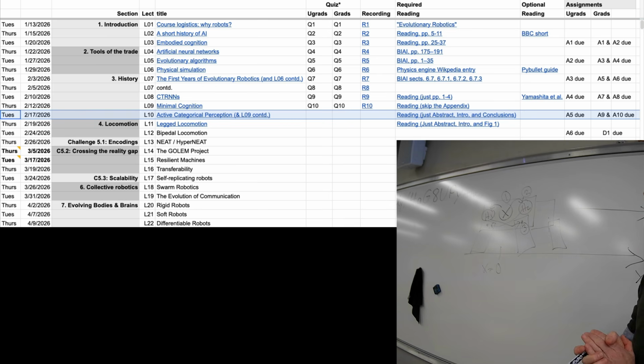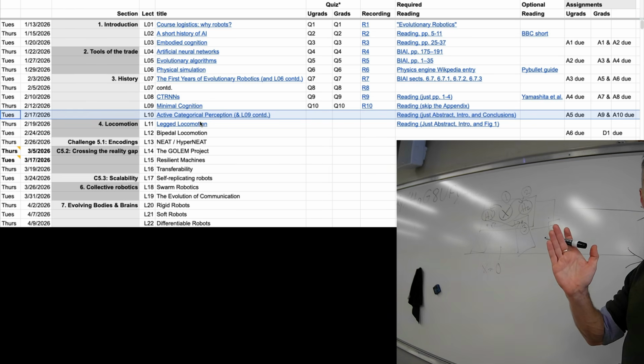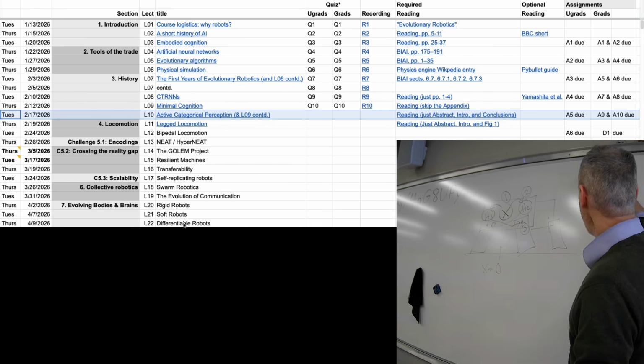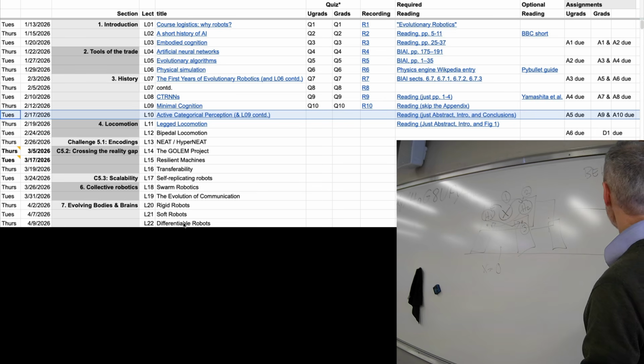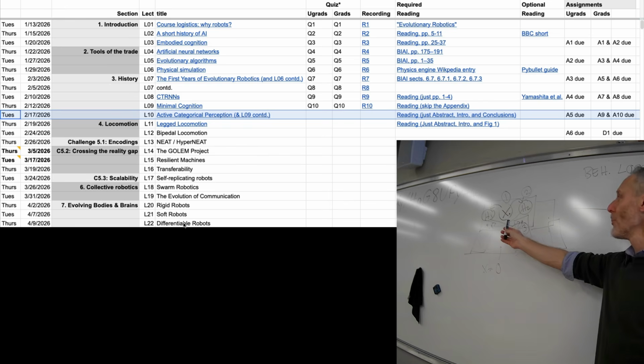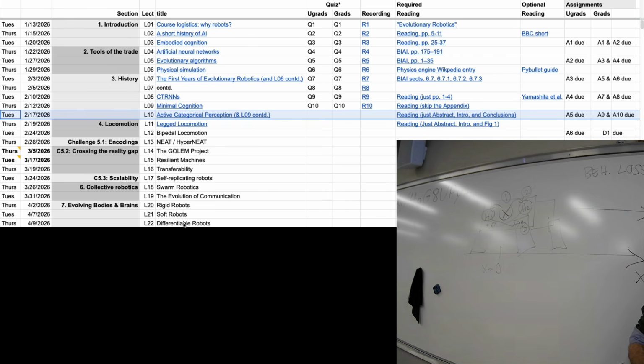At the end of the simulation, we can compute the fitness of the robot, how far it travels to the right. Now the first difference is going to come in from everything you've heard so far to differentiable robots. Instead of computing fitness, we're going to compute behavioral loss. The loss is the term that's often used in machine learning to represent error or inefficiency. Here, it represents the inefficiency in the behavior. How poorly did it do at moving to the right? We could compute this as there's a particular value of x that we want the robot to get to, and if it gets there, behavioral loss equals 0.